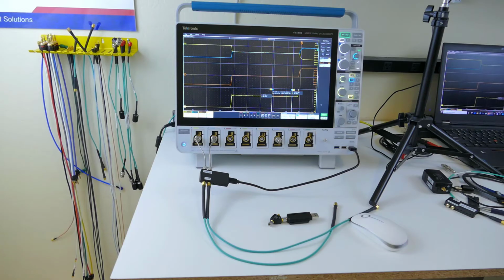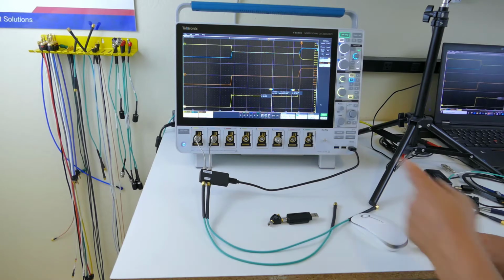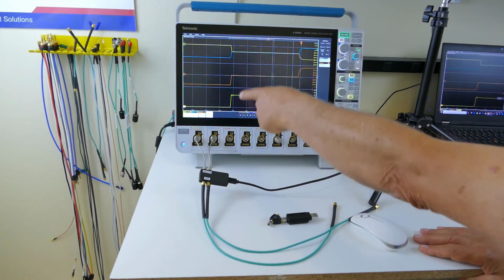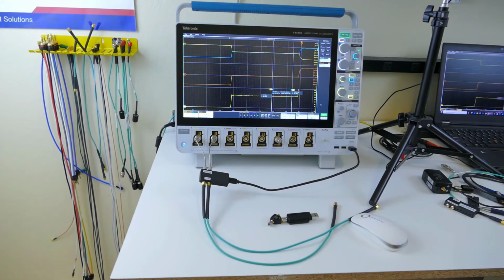So here on the left side, you can see the pulse. And in fact, right here on the screen, at the left edge, that's the launch of our pulse. You can see the two complementary signals. The middle trace is the reflection coefficient ρ. And as you might recall, ρ has a value between -1 at 0 ohms, +1 at infinity ohms, and a perfect match is 0, right in the middle.